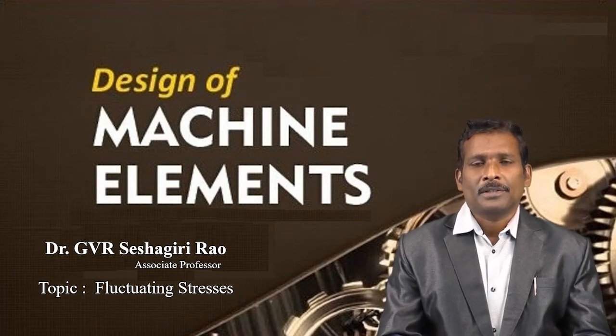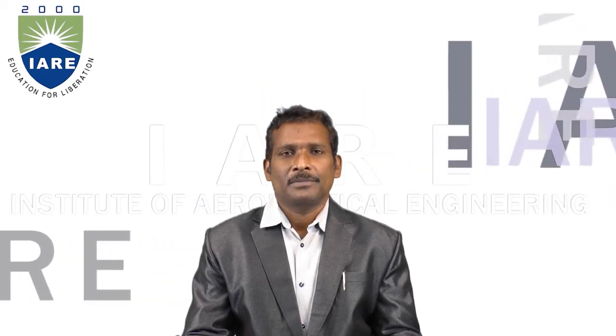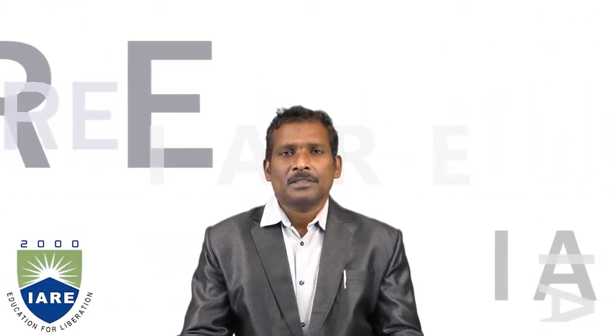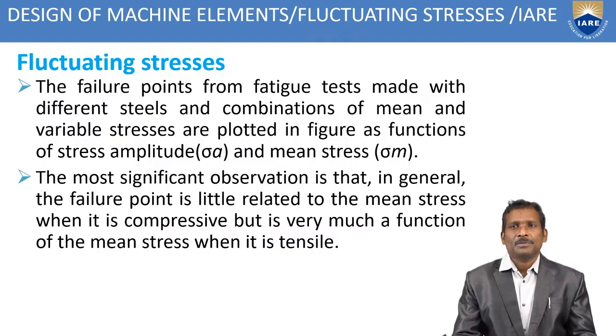Today, I would like to discuss fluctuating stresses. In previous sessions, we have already studied fatigue failure and endurance limit. Now, in this session, we will see what fluctuating stresses are and how to calculate them by using different methods. Fluctuating stresses are actually the failure points from fatigue tests made with different steels and the combinations of mean